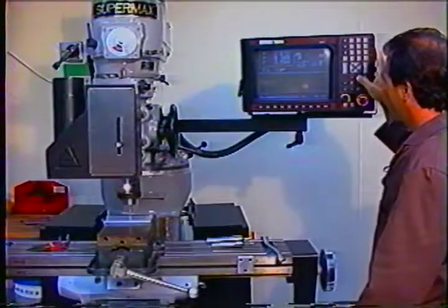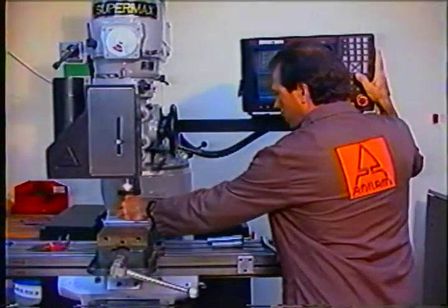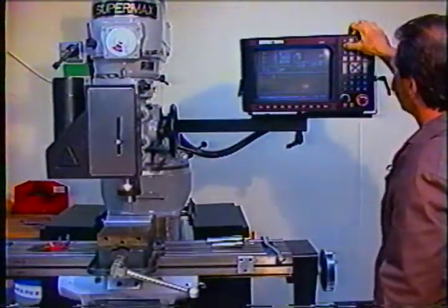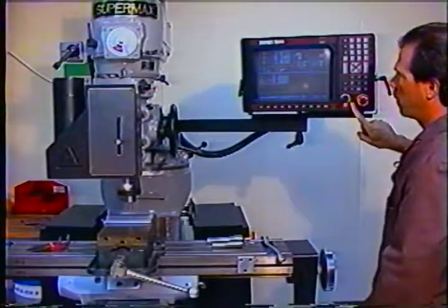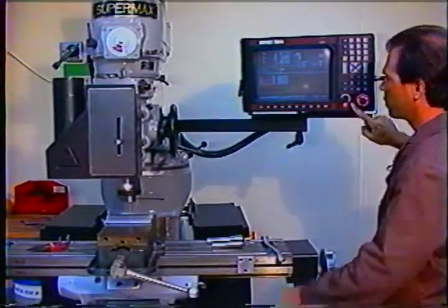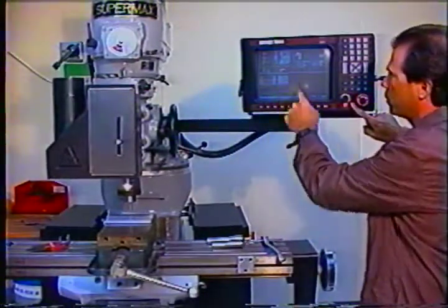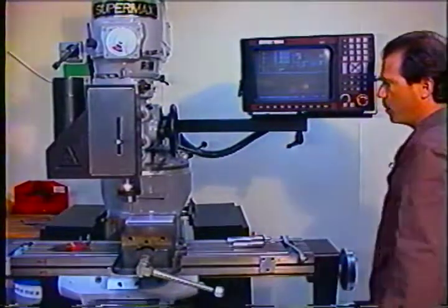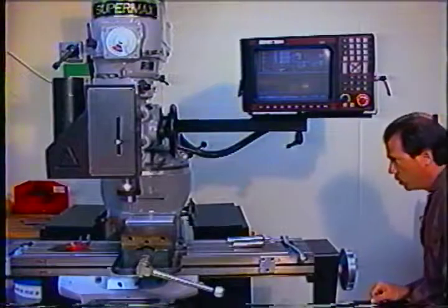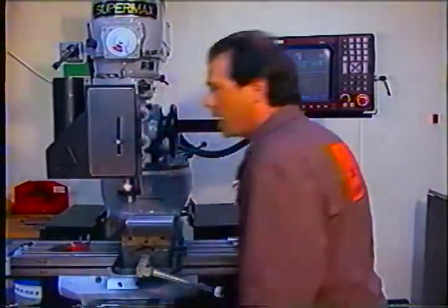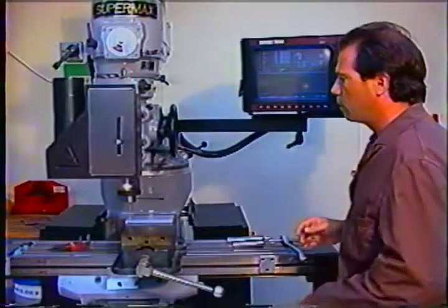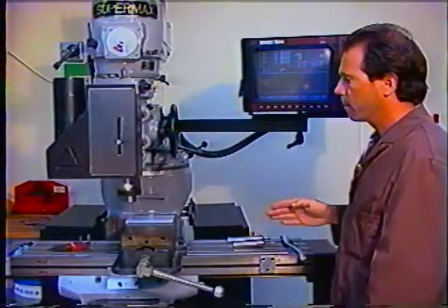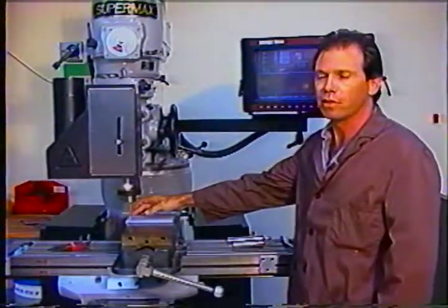I'm going to do a visual inspection by raising Z up. I'll switch my jog back to rapid and press X0, Y0, and hit the start key. As opposed to the enter key, when I press start, the machine will take off to this commanded position in rapid fashion. Okay, so it rapided back to X0, Y0, and I can do a visual check to see that I didn't make a mistake with a positive or negative there. Now that we have X0, Y0, in other words, absolute zero set, that's where all the dimensions of our absolute programming will come from.